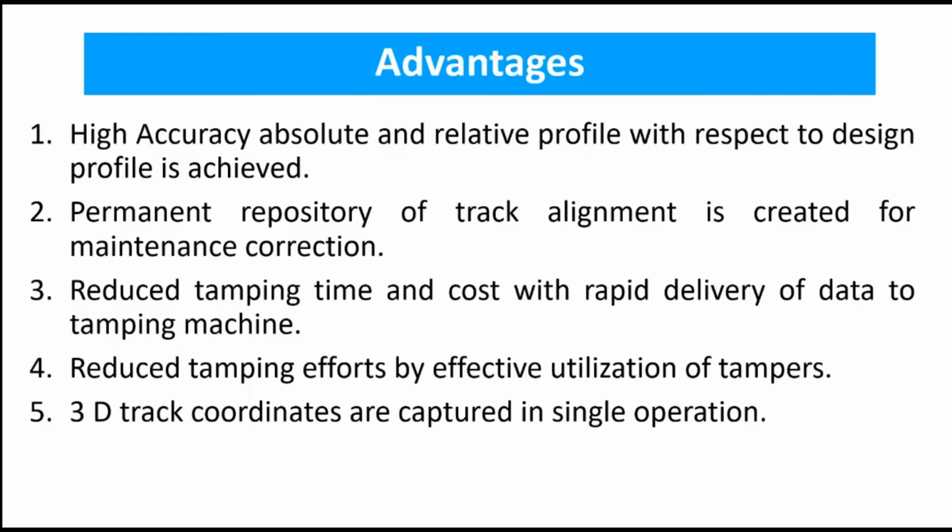When I was in Malaysia in 2006, we were using this coordinate system. Of course, at that time trolleys were not being used. We were using Prism and the total station. So existing track coordinates used to be picked up at 10-meter interval, and we used to compare them with the design profile and then carry out the tamping work based on the survey with total station and the Prism.